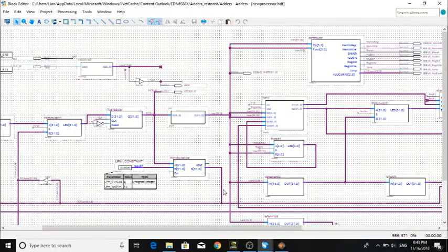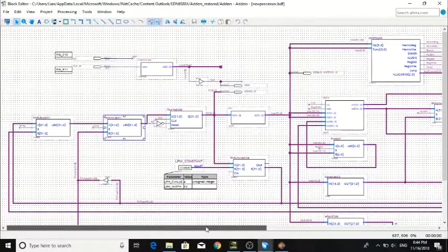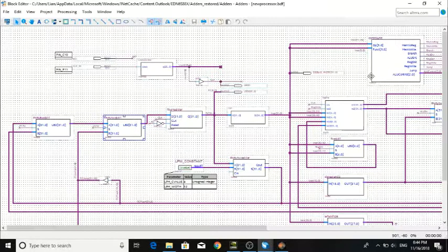Now that there are 30 bits, the last 2 bits are stored on the least significant side, meaning that the last 2 bits are a 00 through left shift, which is here. The high signal from the control unit, which is here, will then allow the address to be loaded into the program counter.